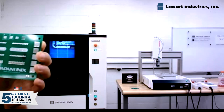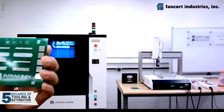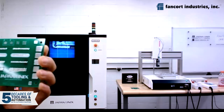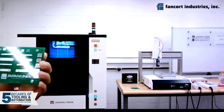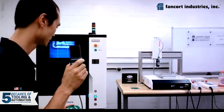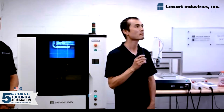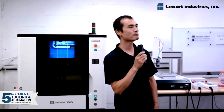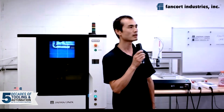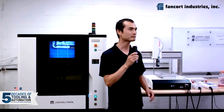We just add solder paste to the pads and then reflow the 9 points at one time, instead of the traditional way to solder point by point. The other question is, is it possible to incorporate flux dispense within the laser enclosure to make the process more efficient? The answer is yes, we can do that.